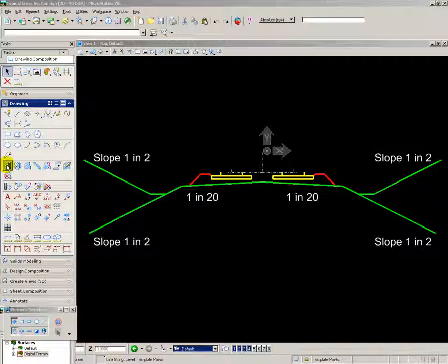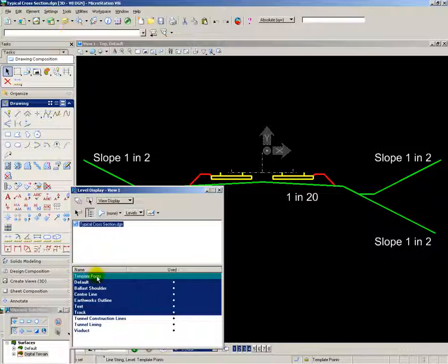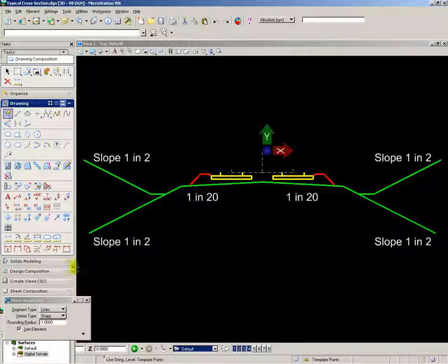For this exercise, I'm going to collect up the key points from the scale drawing and import them into the Bentley Railtrack template. I create a new level called Template Points, and then collect together my key points by digitizing them from the scale drawing using a smart line.